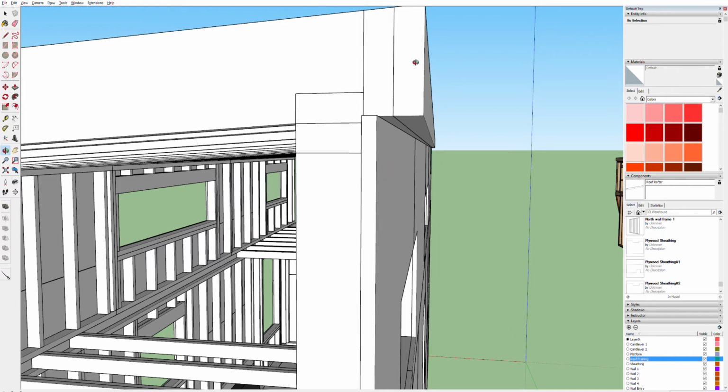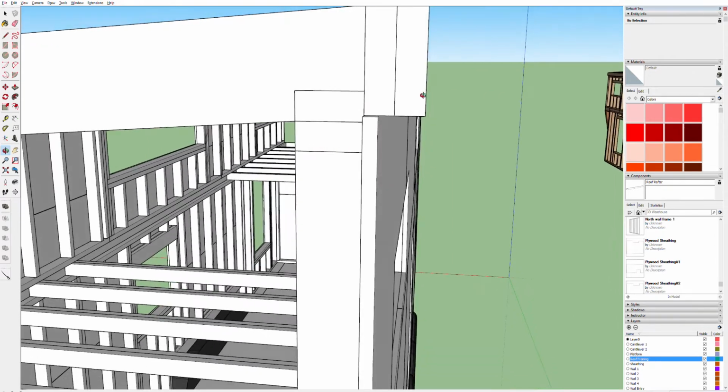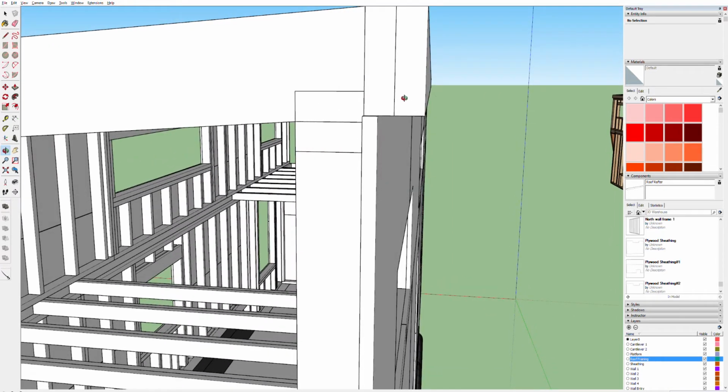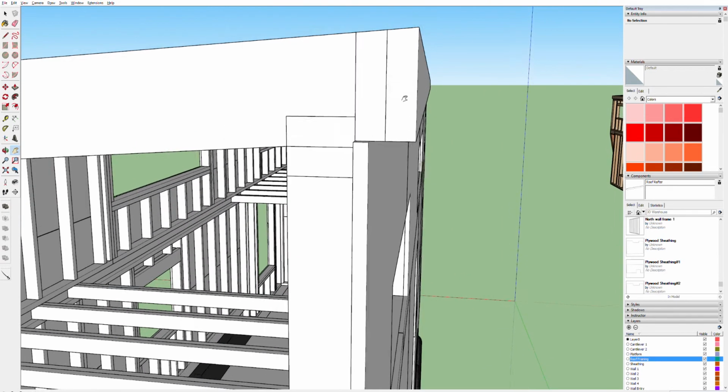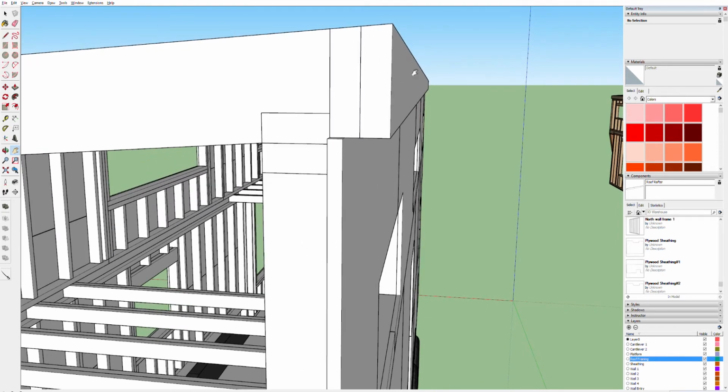So what I have here might be a little bit too much, but I got 3 inches of packed out 2x material coming off the top. I probably don't need quite that much. What I really just want to do is clear, I want to get over all of the sheathing and the siding. So here I've exceeded that by 1 inch.